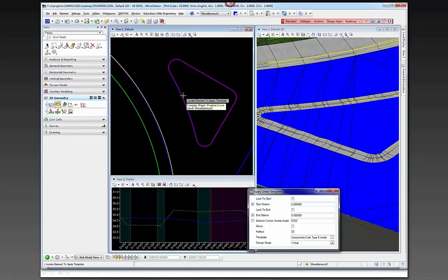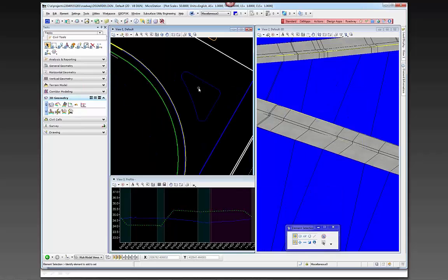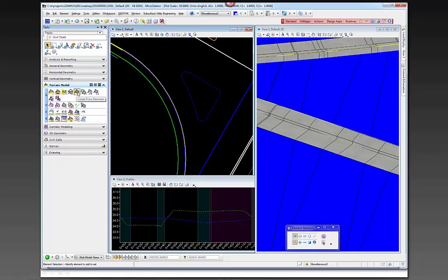Now, it's also created these 3D lines as well, and you could use these 3D lines to clip out this terrain using the terrain clipping tools. So I'm sorry, you want to use just like we did in chapter 1 where we actually created the little clippings.